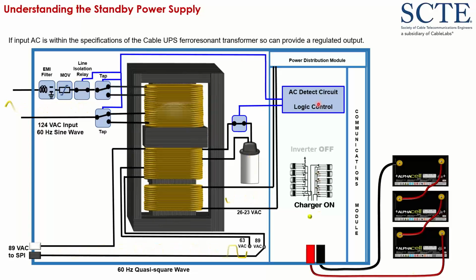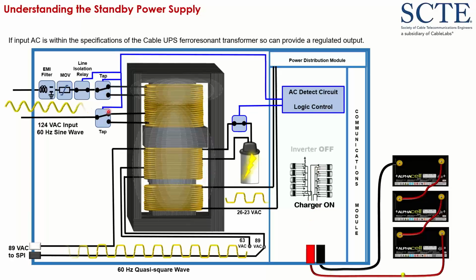Remember, the brain's always watching the power coming in. There are a couple taps here that allow us to change the number of windings on the transformer to adjust the voltage. That power comes in from the utility into my main winding. It produces a huge magnetic field that flows through the core, through the steel, past the magnetic shunt into the secondary windings.